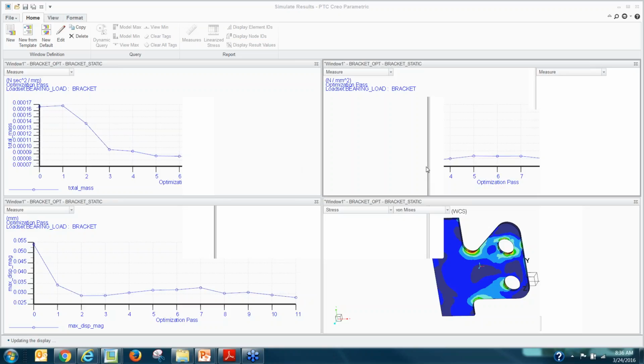Before, we couldn't. So you could have two or three load sets. Once you do the thermal analysis, you can do a structural analysis to account for the stress due to thermal expansion. You would add that as a separate load set when you define your fatigue, and then you can go, say, 0 to peak, peak to peak, etc.